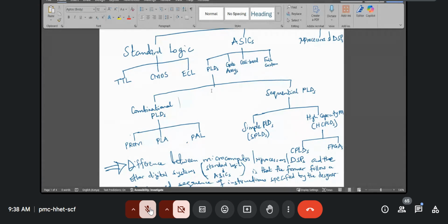But what we are looking at is the very basic ASIC stage, and also the very basic PLD, because the PLDs go all the way to FPGAs. As we shall see, with FPGAs you are not really blowing fuses, and therefore you can change the functionality of the FPGA as often as the case may be. So as far as the fuses are concerned, it is irreversible.